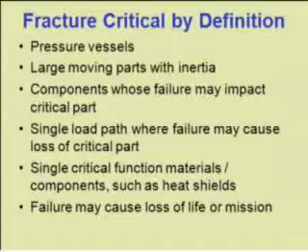There are some articles that they declare as being fracture critical by nature, and pressure vessels are one of them. Any large part that has a lot of inertia can come apart and destroy the system. The third bullet there is any component whose failure would cause loss of life and mission by damage to other areas. Any single load path, single function materials such as components and heat shields, where there's no backup system. And the bottom line is anything that could be shown to potentially cause loss of life or mission.